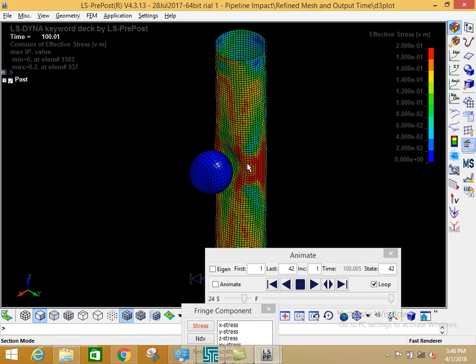That's why sometimes we have something called mesh sensitivity analysis. What does this mean? Meaning we run the same problem, everything exactly the same, only the size of the mesh we change. And we see how much that will change our result.